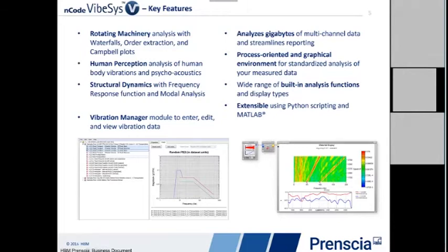And we've got an awful lot of those glyphs, those little icons, each one doing something very specific in the area of signal processing. Here we'll just concentrate on a few of them, the one that computes the frequency response analysis, the one that does the experimental modal analysis, and the one that enables you to animate a structure. But we've got over 100 of these, and if you don't find the exact algorithm you're looking for, you still can script your own algorithm there and lock it down and save it in the palettes. And the scripting language is either Python or MATLAB.